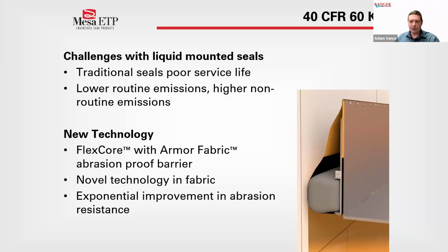These foam seals can put a tremendous amount of pressure on this fabric as they are constantly exerting outward. And over time, this force and friction against the fabric during fill and drain cycles can cause this fabric to fail through wear, rips, or holes. And once the fabric's compromised, the foam can soak up the fluid since it's sitting right on the surface of the fluid, and can cause a seal failure and an environmental headache when being replaced.